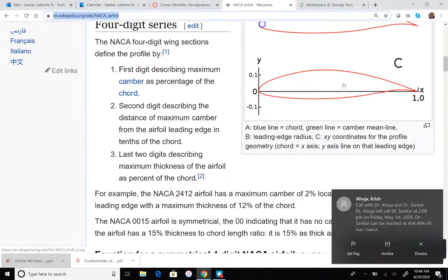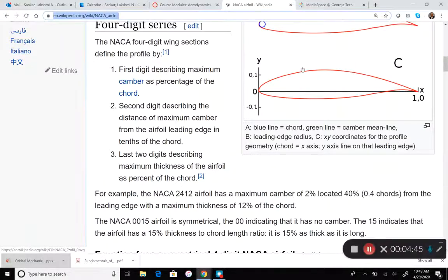But a thick airfoil also means a very heavy wing. Also, if you make it overly thick, the flow may get separated in the back end of the airfoil, causing stall or perhaps at least a rise in drag. So many factors go into play. For this reason, most of the airfoils tend to have about 12% thickness.